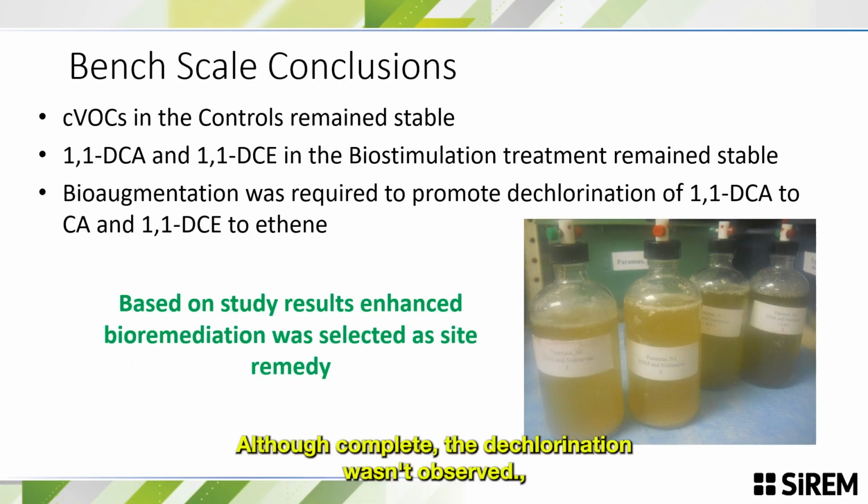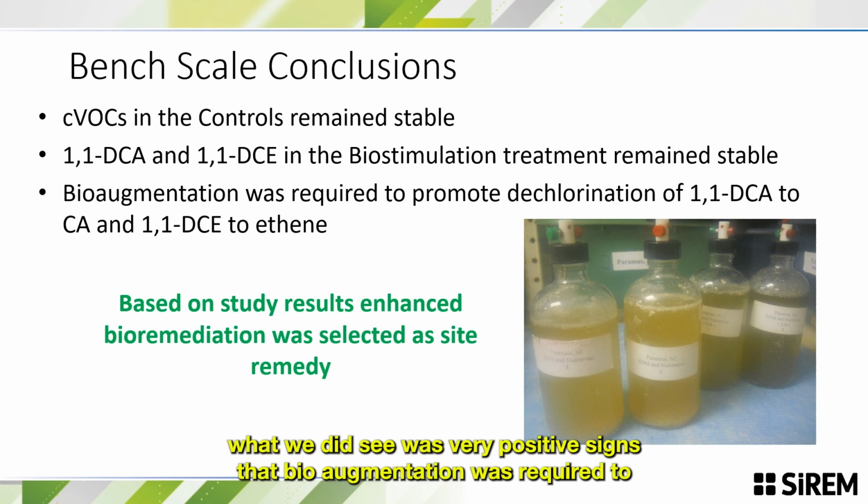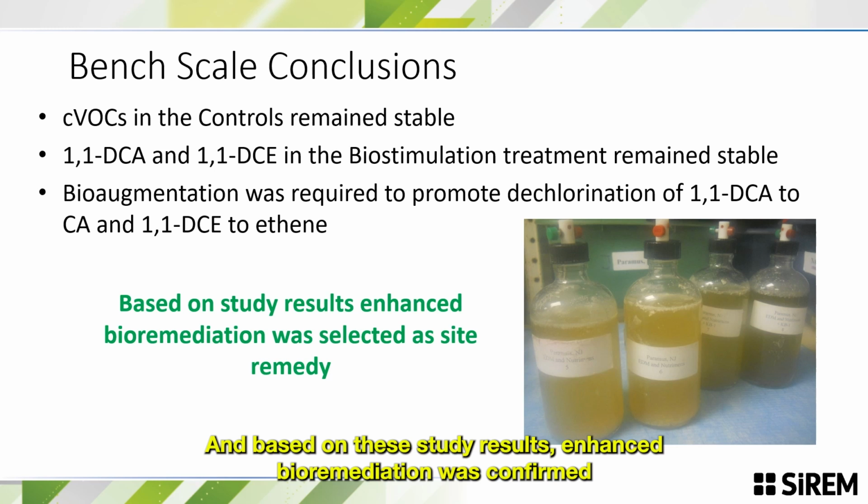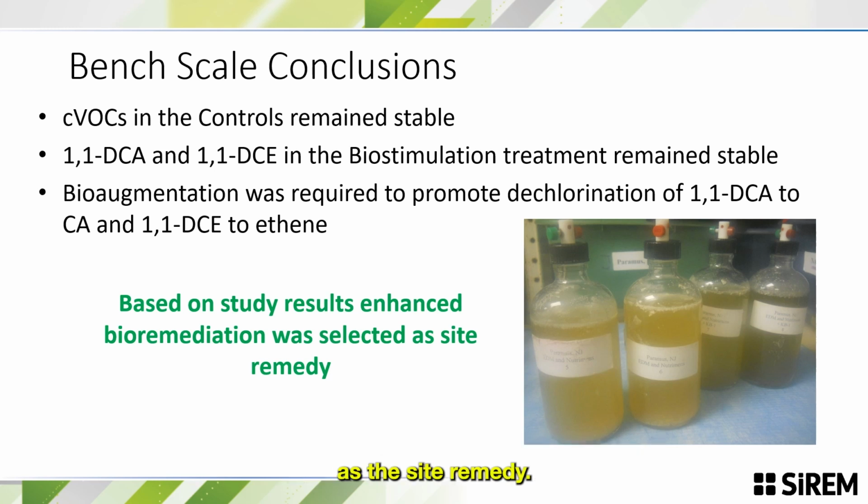Although complete dechlorination wasn't observed, what we did see was very positive signs that bioaugmentation was required to promote complete dechlorination of 1,1-DCA to chloroethane and 1,1-DCE to ethene. And based on these study results, enhanced bioremediation was confirmed as the site remedy.